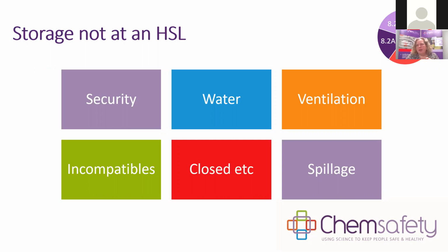Adequate is not defined here, but you would take into account the workplace exposure standards, for example, or if things are only in closed packages, then an inhalation risk is unlikely. We need to make sure that our substances are not kept near hazardous substances which they are incompatible with, or which they might react dangerously with, and I'm going to go into this in more detail shortly.